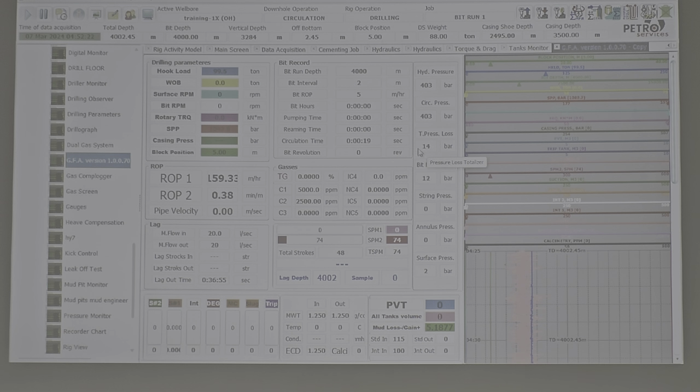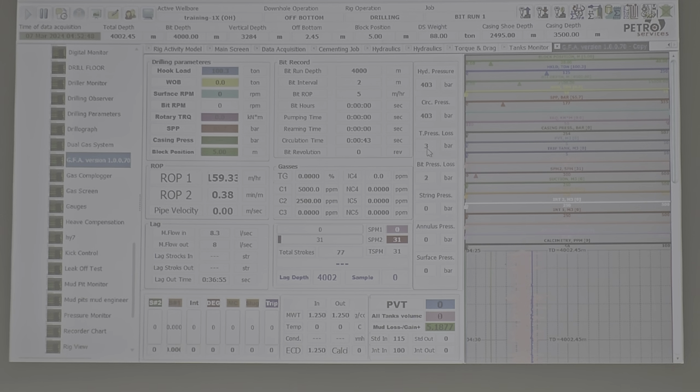So what if this number gets more than this number by 700 bar or 200 bars or something? It should be a problem. You have to check and you have to inform. Also, if they ask you about hydraulics and you go to reality and find a big difference between standby pressure and total pressure loss, it means maybe one nozzle is blocked.